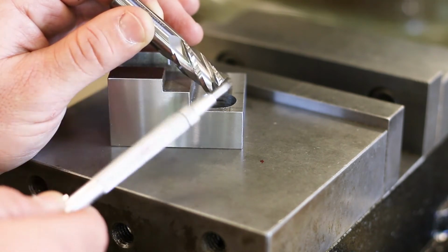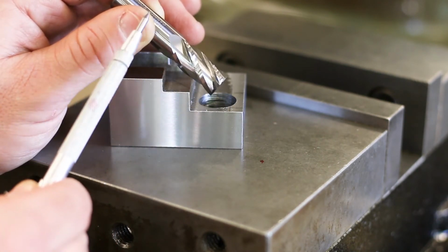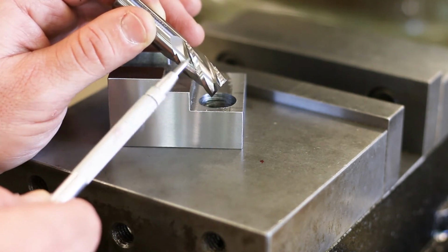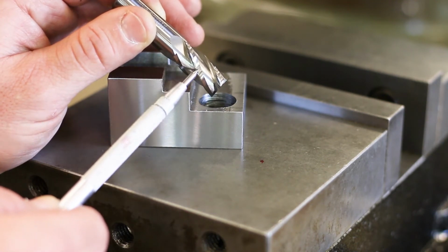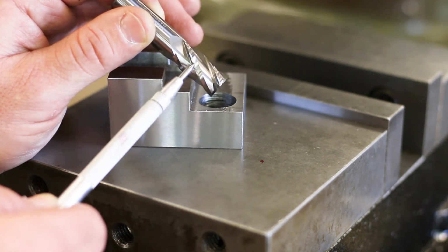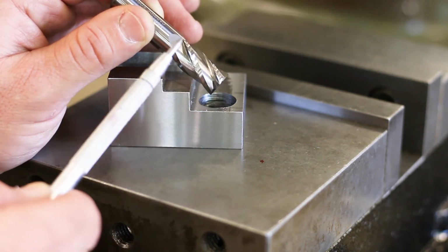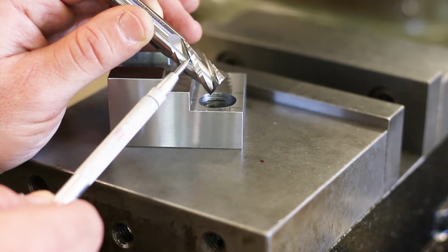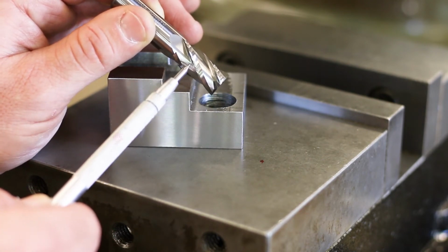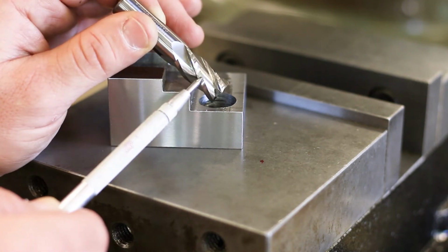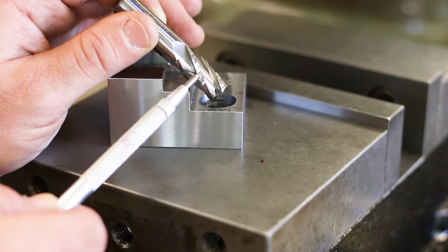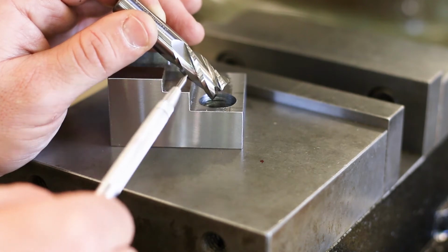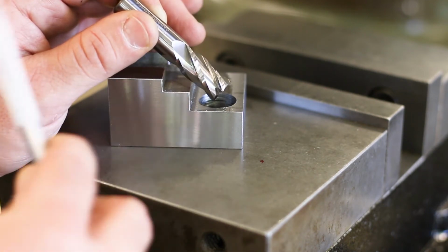Add to that, because it's made out of solid carbide, it's ridiculously expensive. In fact, it's kind of questionable whether or not we should be using these on a manual milling machine at all, right? These are really designed to be used with CNC machines, which have very smooth, very reliable movements, whereas on a manual milling machine, everything's a little bit herky-jerky, especially if you're just learning how to use the machine for the first time. Jerky movements and big bites are the things that really spell disaster for this type of tool. But these tools are very common, and we would like you to learn a little bit about them and get some exposure to using them.